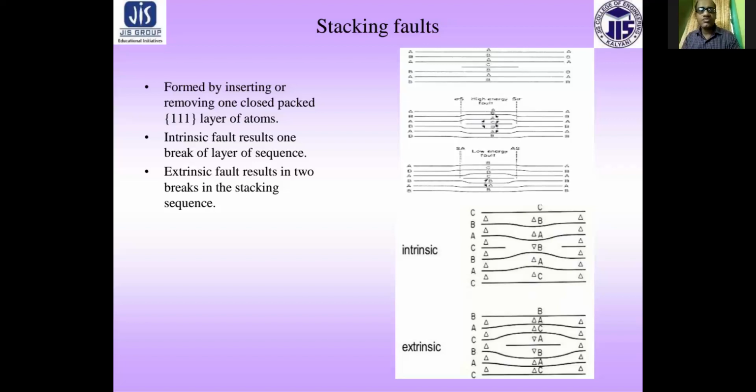Stacking faults are easily revealed after etching by a color difference under the optical microscope, because the faulty region etches in a different manner than the basic region. Such stacking faults may occur during crystal growth or may result from the separation of two partial dislocations.